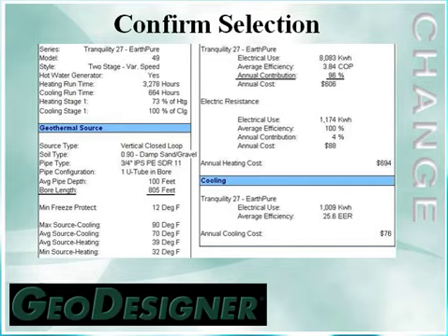The first thing I look at, at the top right, is what percentage of the annual heating requirement is being covered by the geothermal unit. I like to see this in the mid-90% range. We want to do the majority of the heating requirement with the geothermal unit and a minimum with the backup heating system. Again, the big reason your customers are going to buy geothermal systems from you is lower operating cost. In this example, we're doing 96% of the heating with the geothermal unit, 4% with our backup auxiliary heat system.